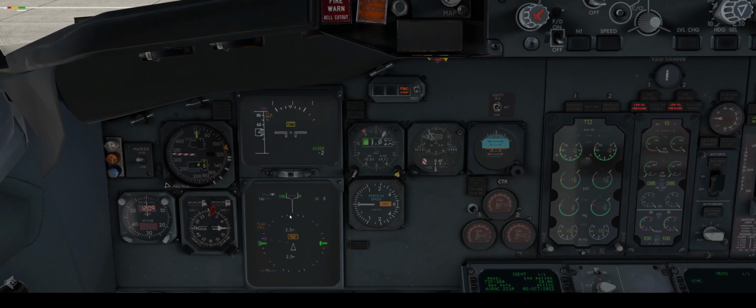Here you can see that the things are basically the same, except that you have the altitude indicator only here. The airspeed indicator you have as well on the AIDA panel, and as well you have this classic indicated airspeed indicator, but here you are adjusting your baro settings, and this is your minimums. Okay, so with this knob and this yellow bug you set up the minimums.